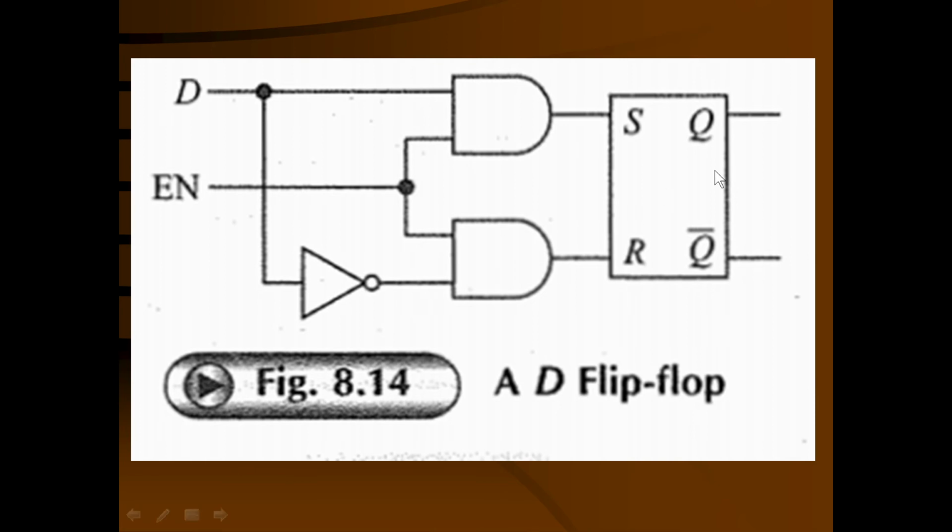So you can see that this is your basic RS flip-flop, which has two inputs, S and R, and two outputs, Q and Q bar, which are supposed to be complement to each other. Prior to that, two AND gates are introduced, and in the two AND gates, one of the inputs is shorted and it is called the enable input. That way, this is your clock RS flip-flop. Now, here it was the S input and here there was the R input. Between these two, one more inverter is placed at the input side. And that way, the clock RS flip-flop is converted into the D flip-flop, and this S input is designated as the D input.